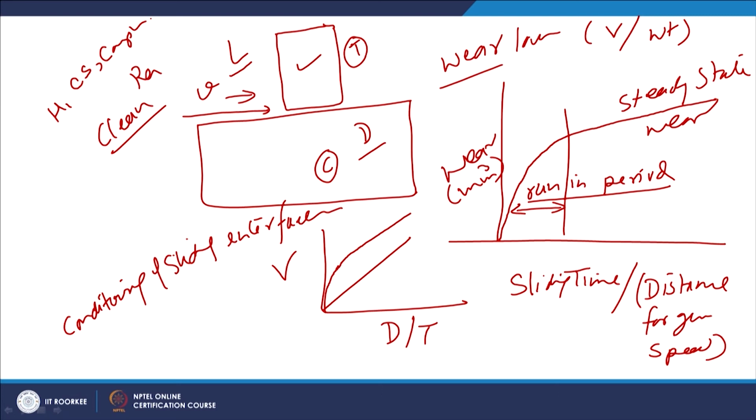But whenever the two start interacting with each other, the surface roughness will change. Due to the interaction, frictional heat is generated, so oxides are formed at the interacting surfaces. Oxide layers will be formed on both sides of the components, and there will be continuous exchange of the constituents from one side to another. So, we can say metal transfer takes place across the interface.